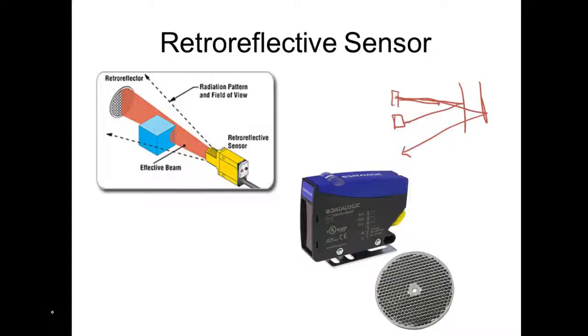And that's not exactly true. Some of our sensors are 24 volt sensors. But what we'll have is a DC power supply that will plug into 120 volts to power the 24 volt sensor. Some of your sensors are not available. And this is what you would do in the industry. So saying you got a 24 volt sensor, all that means is that it powers up off 24 volts.